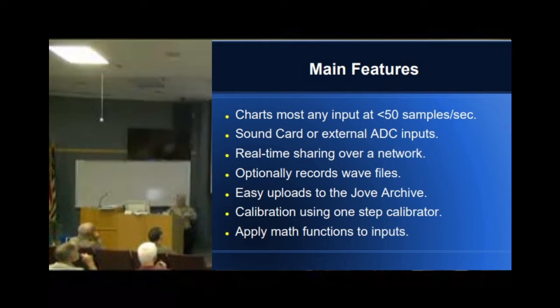Radio SkyPipe is not intended to sample at high rates. 50 samples a second is maxing it out. But we don't need it for Jupiter. We're good at about 10 samples per second to see the fine detail.